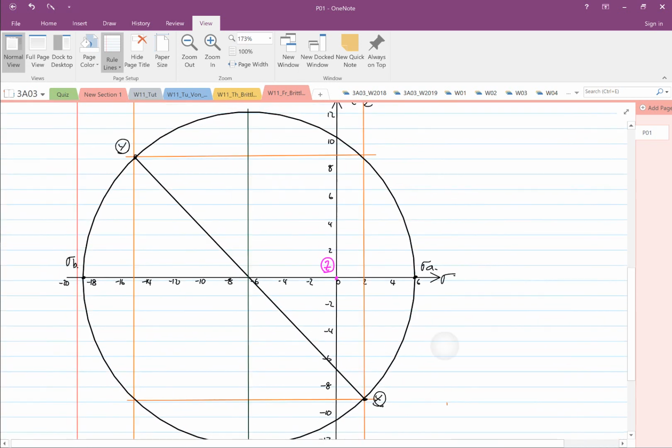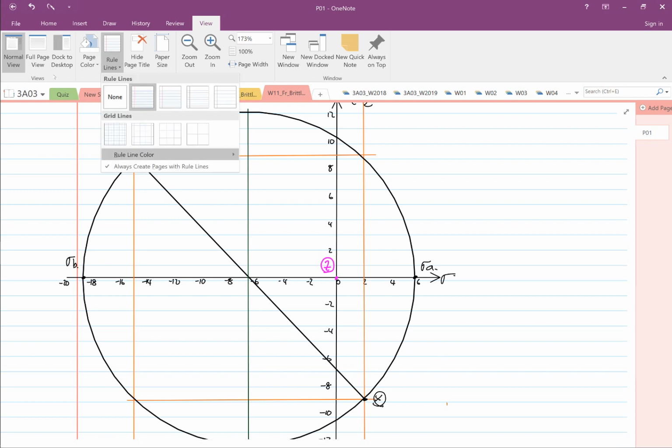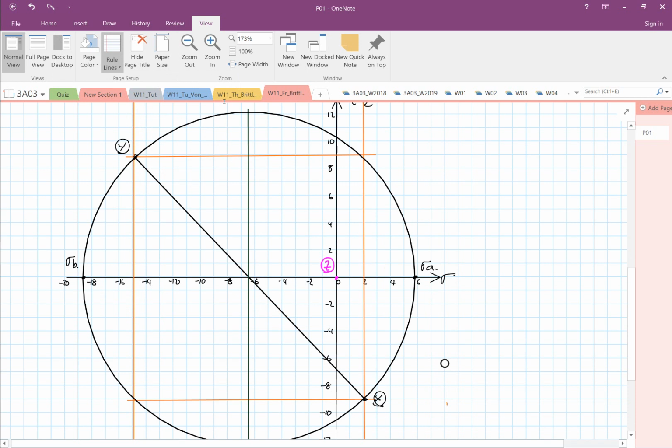So I was going to complete the 3D Mohr's circle. You may ask me, why do we have to complete the 3D Mohr's circle? I know it's obvious now, but we know that this is a 3D element, where stress Z is equal to 0. We want to make sure that this is our stress A and this is our stress B, and that point Z is not on the outside. Or if the circle is shifted, stress A can be at point Z. So the next circle that we're going to draw,